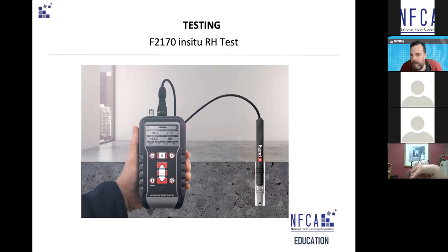Anyway, this is where it gets sciencey, but basically, because of the alkalinity of concrete, you can have humidity saturation above 93% RH. That means a slab at 99% RH is going to have less moisture than a saturated slab at 93%. And that's where the problems come.